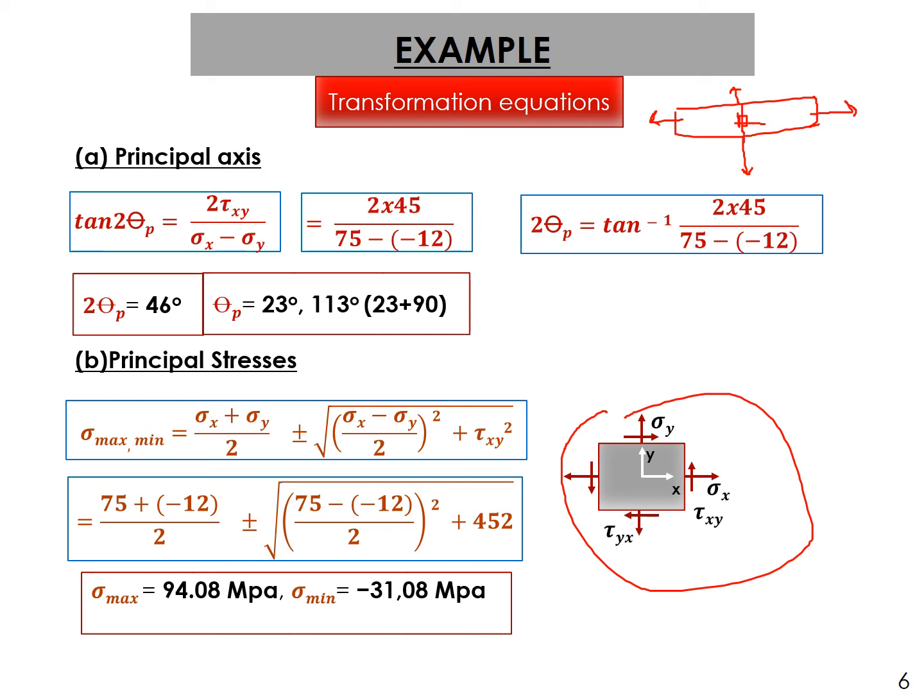Because of certain conditions, the load might get shifted. The load might act at some other angle, because when the machine is on, when the vehicle is moving, wear and tear will take place. The line of action of the load may change. So we try to explore all possibilities and find out the maximum load acting on that element. That way we show what the stress is at this angle. We go on calculating the stresses at different angles. And at the principal axis we know that we get principal stresses and maximum stresses. So what I was telling you is that the rotation of the element has been shown for simplicity, so there shall be no misconception.